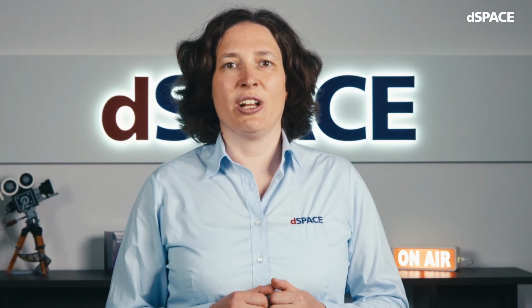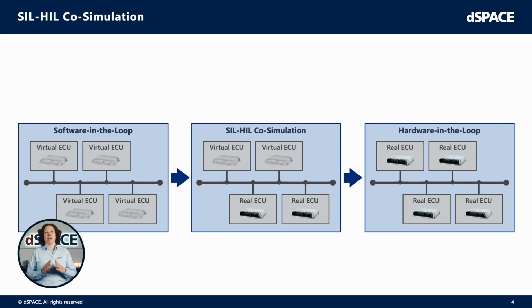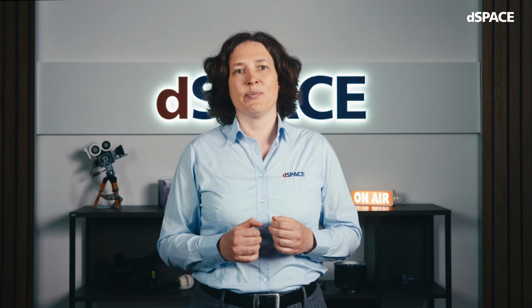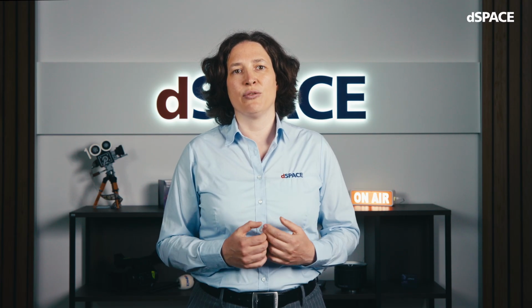With SIL-HIL Co-Simulation, we are changing precisely this approach. Instead of separate test worlds, we enable a common simulation environment. Parts of your system run virtually in SIL, other parts already on hardware, and both are tested synchronously together. This means that integration scenarios can be tested much earlier and more realistically than ever before.